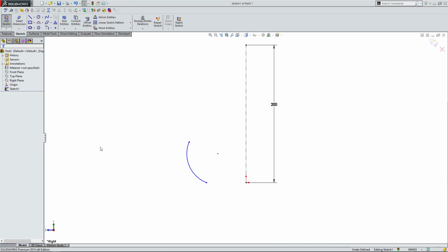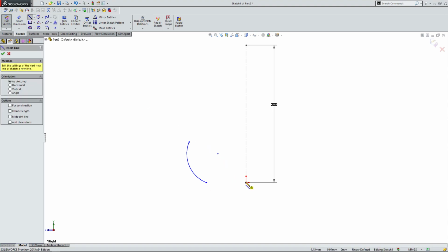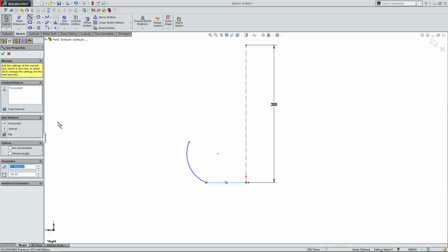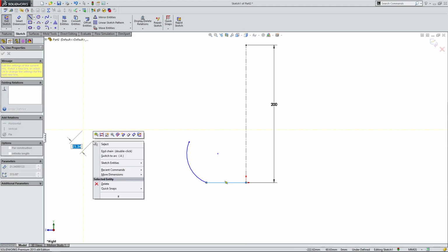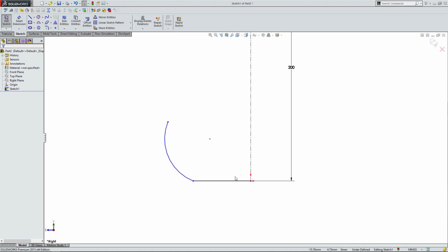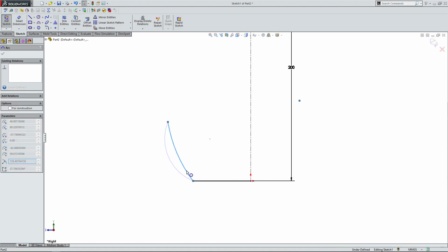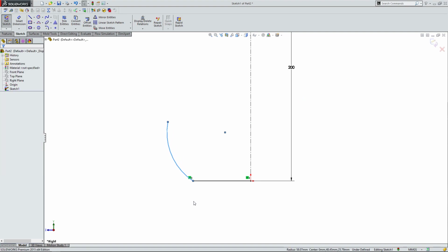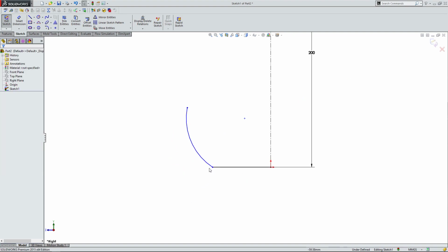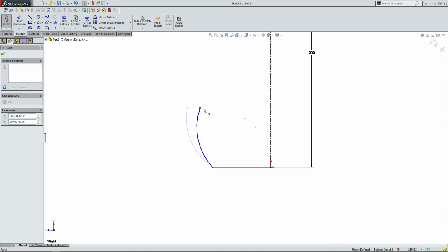That's the first thing. Now I need to connect the origin and this point. So let me come up here and create a line between here and this point. Now they're connected, but you may notice that they're not tangent to each other. So I don't want this sort of sharp edge here. This is not uniform. This isn't going to look good. This isn't going to even work well. This may not even be blow molded properly because of a sharp edge. There may be problems in manufacturing.